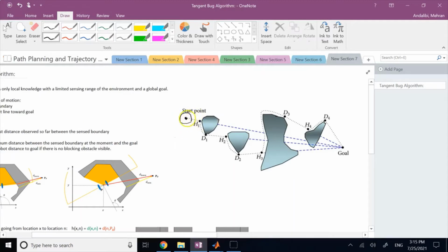And most of the time, your range sensor is not scanning all 360. Sometimes it does, sometimes it doesn't, right? Sometimes all your range sensor can measure is maybe 100, 120, 150, 180 degrees or so. It's not going to scan all around you unless it's a spinning sensor, like a scanning LiDAR. Yes, they scan all around you, but when you're going forward, unless you want to make sure nobody is hitting you from behind, if it's a static environment, then you might just go straight.